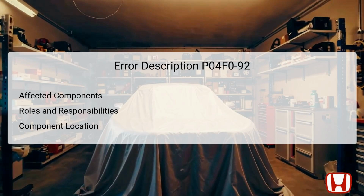The EVAP canister purge valve is responsible for controlling the flow of fuel vapors from the EVAP canister into the intake manifold to be burned. The ELCM works to check for possible leaks in the EVAP system. Each component is located at critical positions within the vehicle.